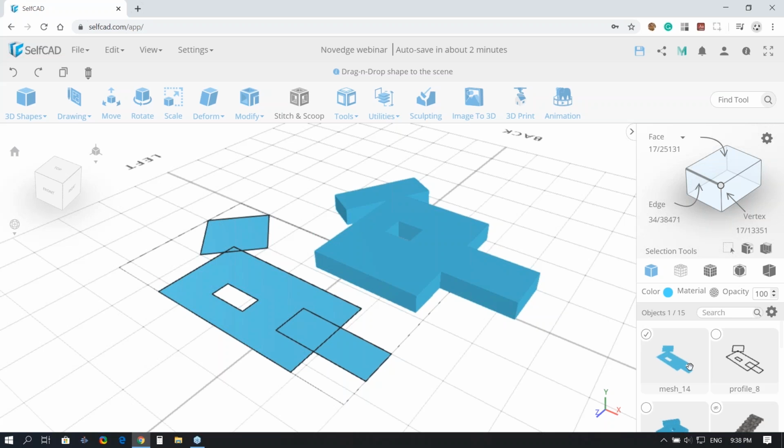In that case I first went to the flatten tool, and I flattened it completely. Then I went to remove duplicates, which removed most of the extra details. Then I reduced it to the 100,000 limit, and I got it. But this is kind of an underused tool. It's really powerful as a way to reverse engineer a lot of complex profiles and so on. That's why I use it.